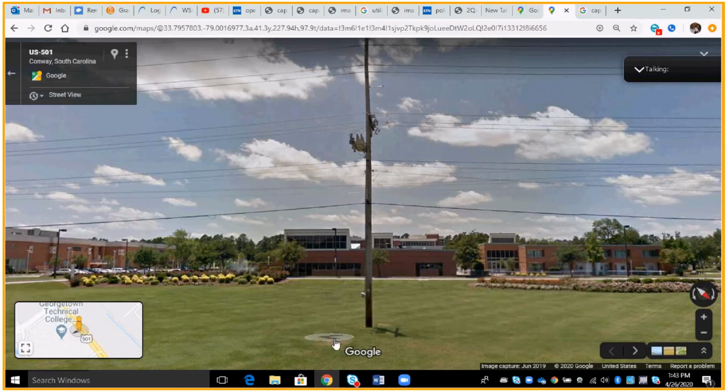So at all times, even if you're on the ground, have your hearing protection on in case one of those fuses decides to blow. If you remember, in the close process when we have SCADA, we're actually able to move over here somewhere and get away while those vacuum bottles close on the bank. Have your hearing protection on even over here too. If something goes wrong and that fuse blows, you've got your hearing protection on.